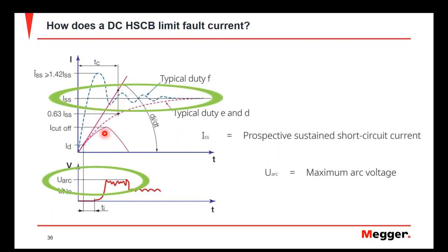And what we do by doing this is we limit the amount of short circuit current or fault current that's developed whenever this occurs, but also we limit the amount of arc fault energy that's created. Because of the opening time, the amount of arc fault energy that was produced is very low, as we can see down here where our curve starts to increase.